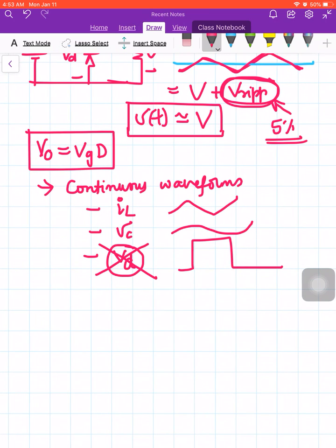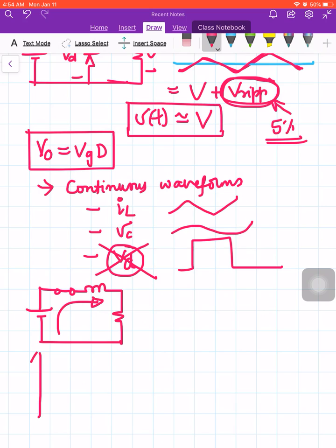So let us try to use this and try to derive our chopper equations. So we have already seen that when the switch is turned on, we have this sort of circuit, and we have also emphasized that the time constant of this particular current, let us say if we solve this circuit, the current reaches a final value equal to Vg by R, right?